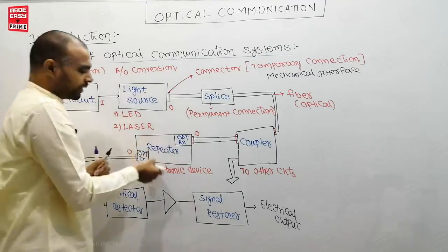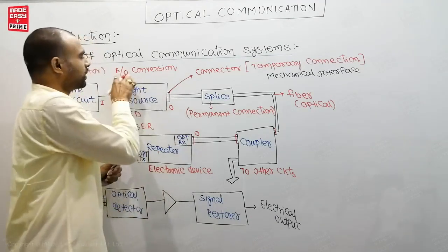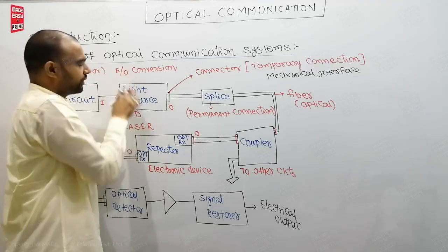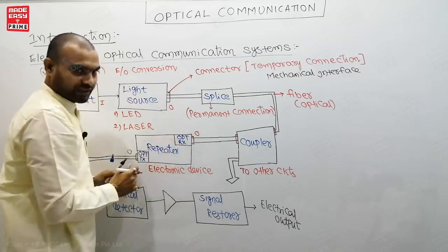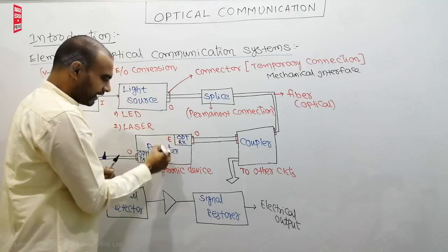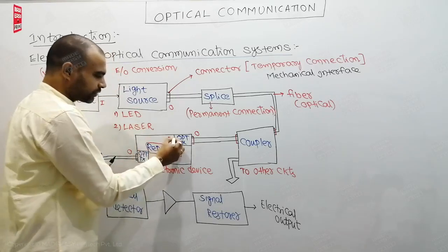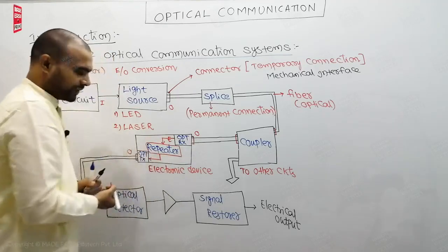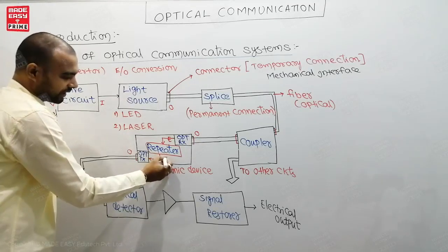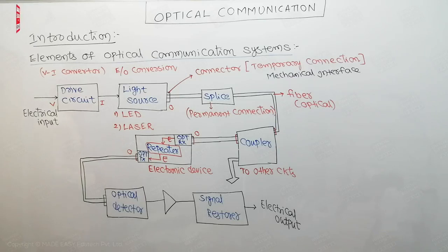But the device works in terms of electrical signals. So we use a receiver, which is the reverse operation of your transmitter, an optical to electrical conversion. So here we get electrical. In the repeater, the electrical operation is performed, and we give that to the transmitter. The transmitter will convert that electrical once again to optical and pass it into an optical fiber.